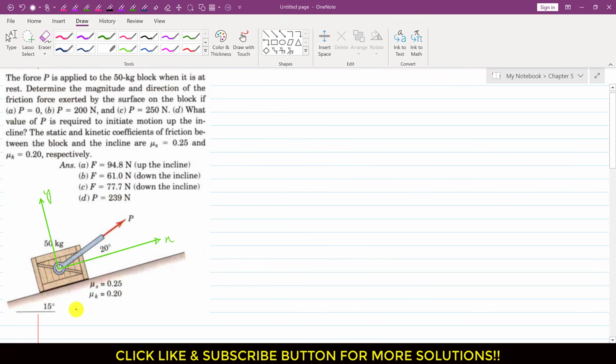Now, as we can see, this surface will apply the normal force on this 50 kg block. So let me represent that normal force. That normal force will be acting like this, in the positive y direction. Let me write that this is the normal force. And then the weight of this block will be acting downwards. So let me draw that weight as well. This is the weight which will be acting vertically downward.